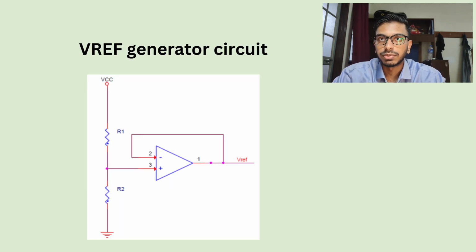Now, let's have some additional information. This right here is a VREF generator circuit, as well as the diagram shown. This voltage reference component provides a stable precision reference voltage for the analog resources such as the biopotential in this oximeter design.